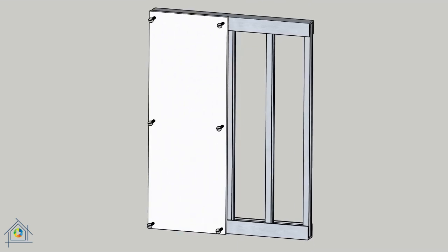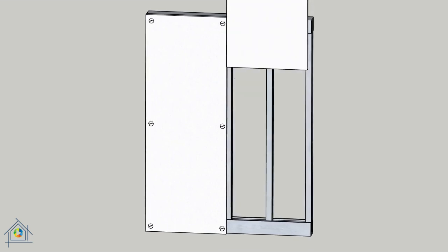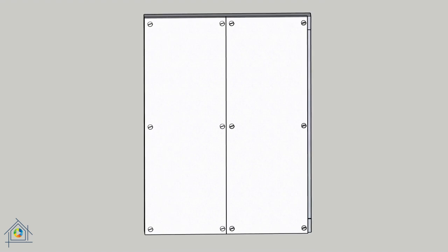Prefabricated gypsum boards are installed on the LSF structure. These boards are connected to the LSF structure using screws. The screws used are 2.5 centimeters long and 30 centimeters apart for installation.